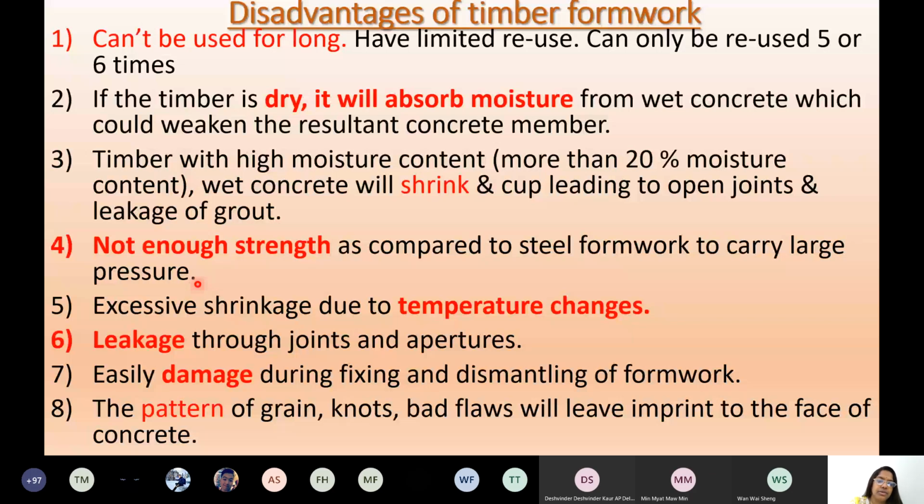multi-stories, right? You can use it for residential buildings up to 2-3 floors, shop lots of 2 floors, 3 floors. High-rise building, you have to go for steel. Although it has some advantages of being affordable, being handleable, customizing is easier, you have to avoid it for high-rise buildings due to its strength and other defects.